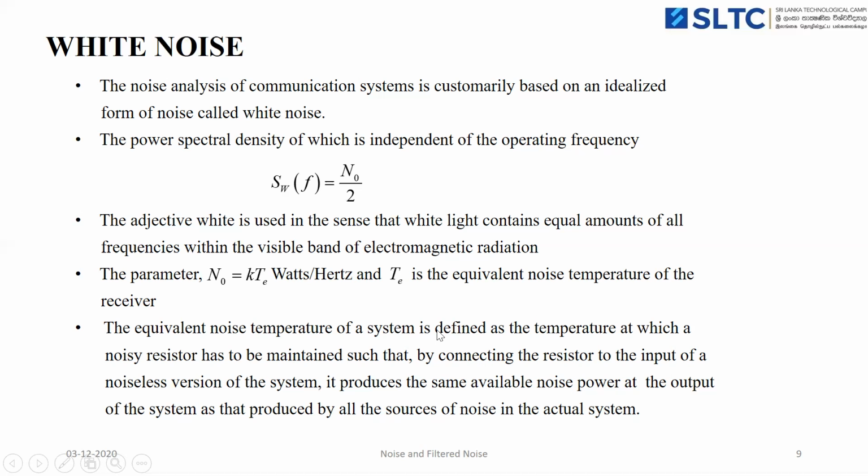Again, the equivalent noise temperature means, at a temperature, while connecting a resistor to the input of the noiseless system, the system produces the available noise power at the output of the system. This available noise power of the system is the same as that of the other sources present in the actual system. Then the temperature is called the equivalent noise temperature, right?